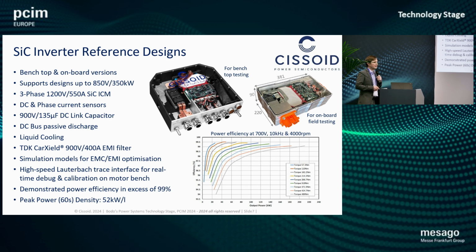Finally, to support customers in their inverter design, we offer two reference designs: a first one for benchtop testing and a more compact solution for onboard testing. This reference design includes additional functions like EMI filters, current sensors, also a function for passive discharge, and we've demonstrated power efficiency in excess of 99%.